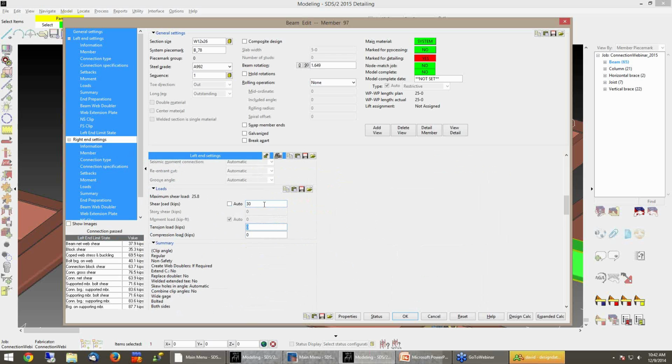What you have to be careful for there and watch out for there is by doing this, there's a portion of connection design that is left out, and that's the framing situation part of this. So basically what this means is when it designs on the fly, it's only designing the connection for the member that it's framing to, and it's not looking at clearance issues that other members framing nearby might present. So something just to be aware of with that.